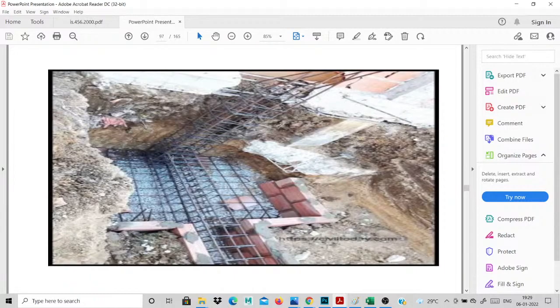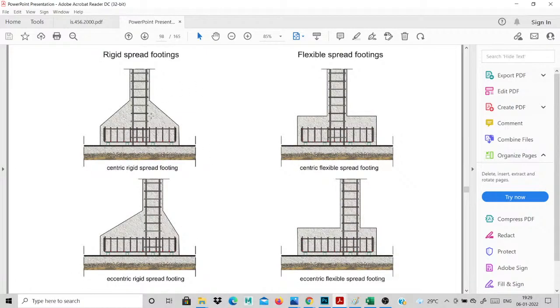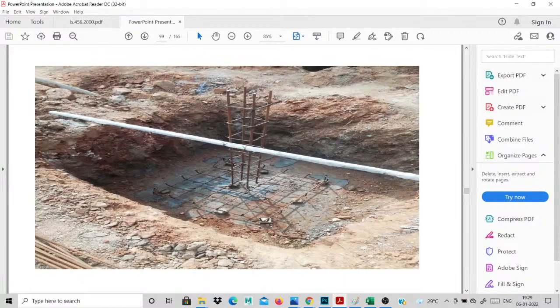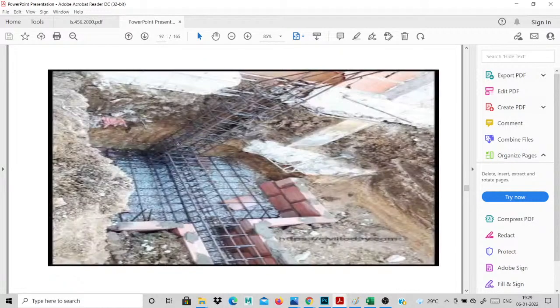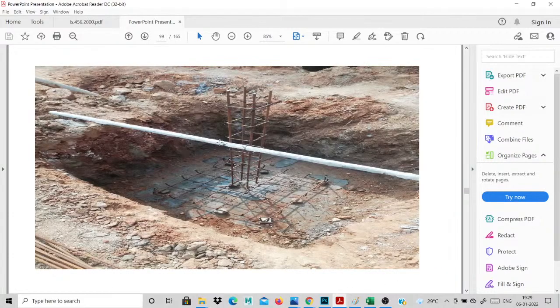Okay, this is the column deflection. It will be connected with all the columns. This is called eccentric footing. There are different types of eccentric footing. This is a normal isolated footing, a single column, so automatically this is our normal isolated footing. It will be taken as a simple method. This is the center of this column. An eccentric footing is for a corner column, and this portion is the center of your column. That is the difference between eccentric and this type of footing.